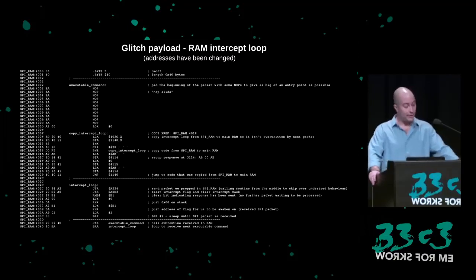There are multiple scenarios possible in addition to my selected glitch target. Stack corruption is a possibility, and really any abnormal program flow has some possibility that it could eventually land in my code. The von Neumann architecture without strong memory management is a very fertile ground for glitching. Anything in RAM potentially could be executed. So at this point, there are several uncertainties, but so far nothing totally rules out the possibility of success.